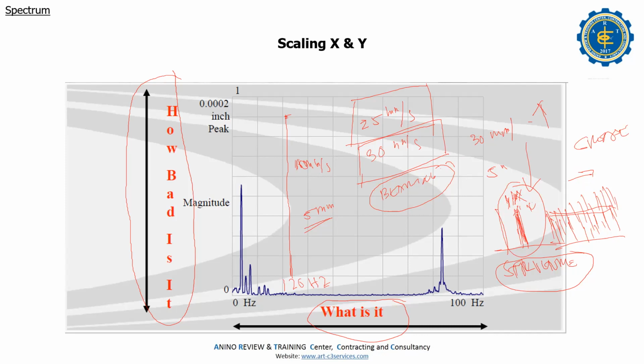If the vibration is steady, then up, up, up, so there's a tendency that it is an unbalance. That is normal for the fan because it is dusty. The dust accumulates on the fan. Just monitor, not directly shut down. Only the bearing is the issue.